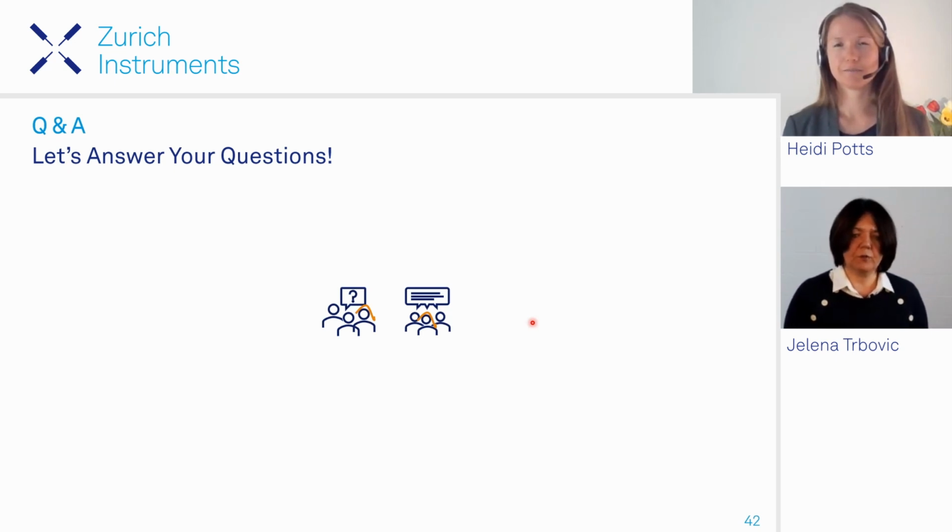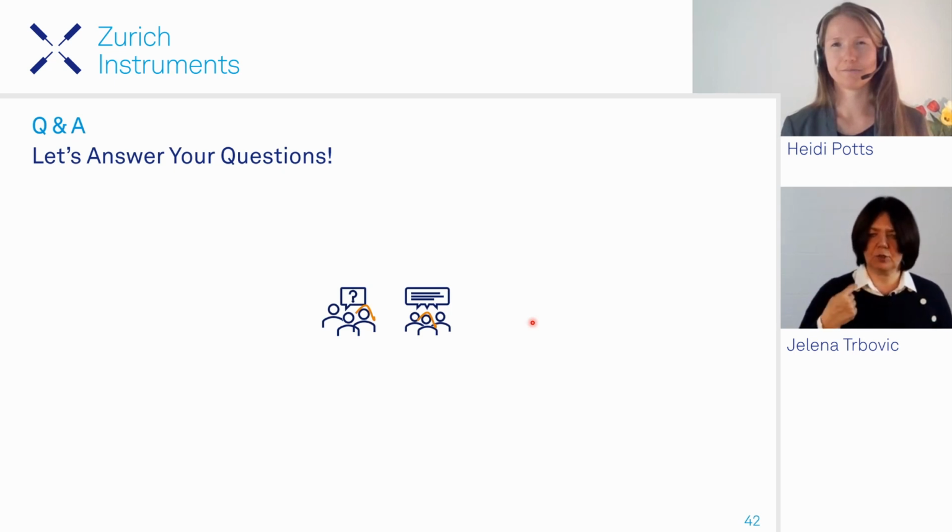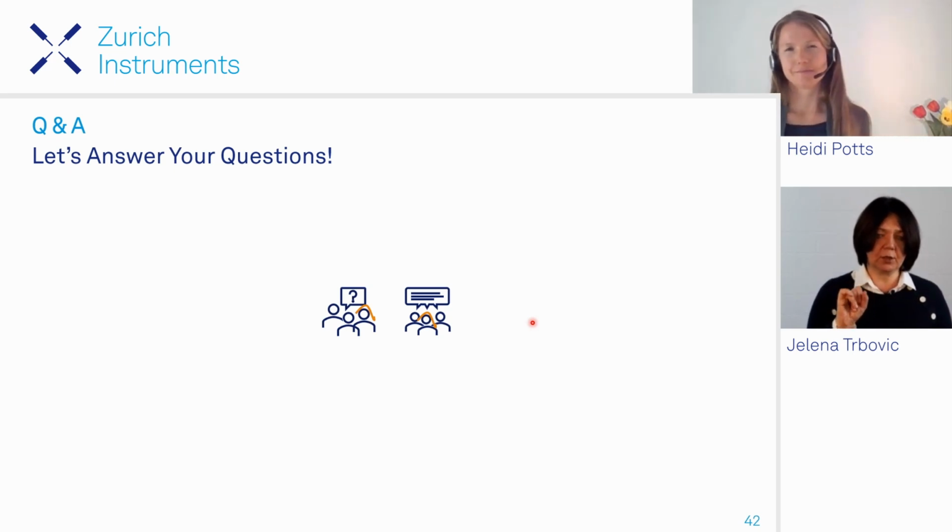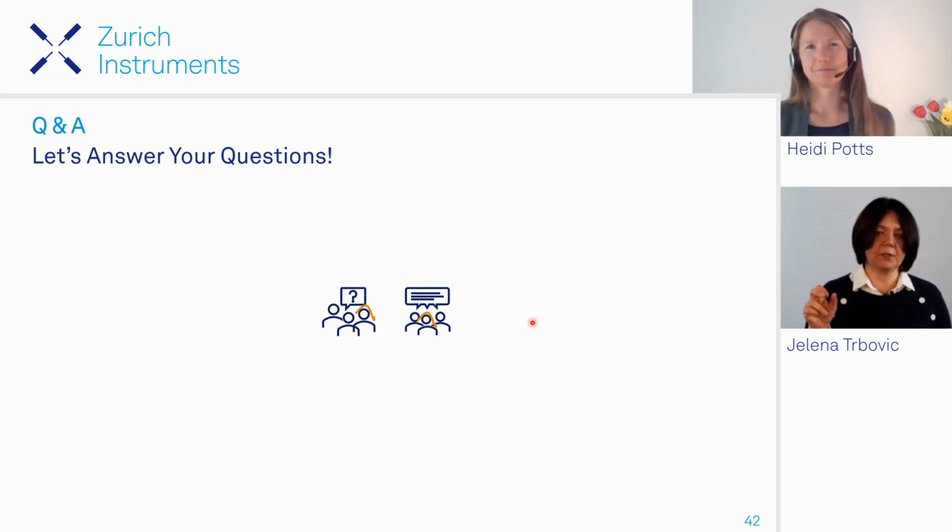Yeah, there's also mention of speed over here for DI/DV measurements. Maybe just to add on top of that: depending on how good or bad your signal to noise is, what will ultimately determine the speed of the sweep is how much noise you have. If you have a lot of noise in your system, then you really have to reduce the filter bandwidth or increase the time constant.